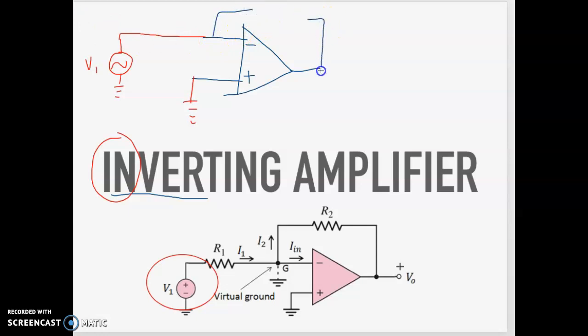So what is the role of feedback? To control the gain. In the feedback you have one element called R2 or RF, which is what we call the feedback resistor. And where is your output connected? At the output here. Okay. So why do we call this an inverting amplifier? Because your input supply is connected at the inverting input. So in between this point, what we call virtual ground.